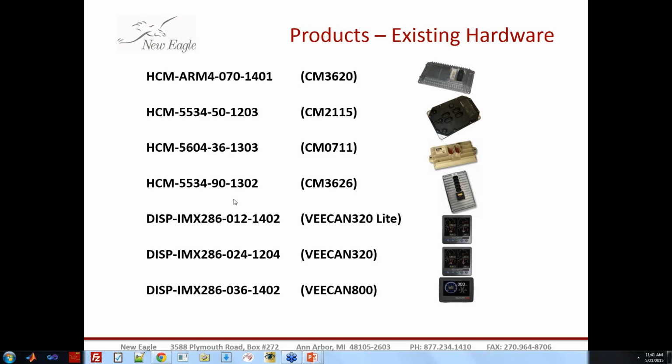So with Raptor telematics, can you read any parameter that you can see with Raptor Cal, or do you need to be sending it over the CAN bus? Presently, it's mainly DBC related, so anything that you could see through a DBC file. In future versions of the product, we do envision having XCP calibration support, so we could reach in and look at adjustments and measurements within your model, but that's not currently supported.